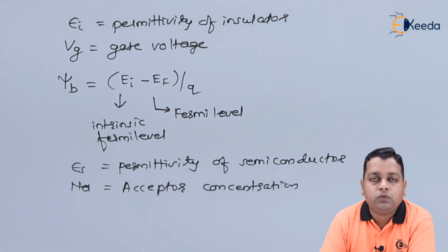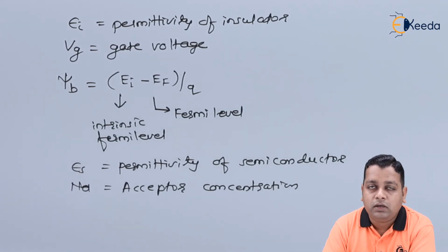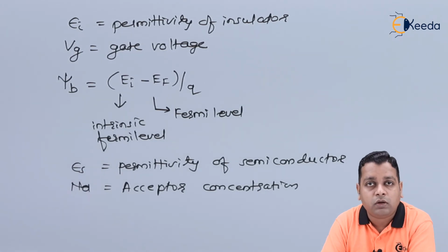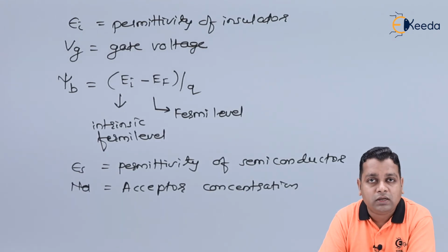Now, we have just seen the equation that represents the drain current dependent on various parameters. In the characteristics, we have seen the nature of the drain current to be linearly increasing in the linear region, then constant inside the saturation region. So we modify the generalized equation as above into the linear region and then into the saturation region.